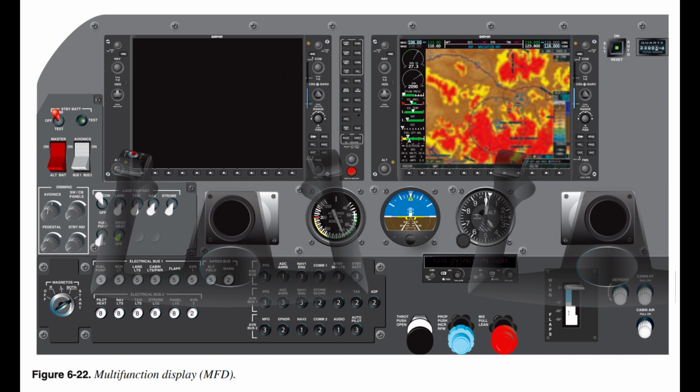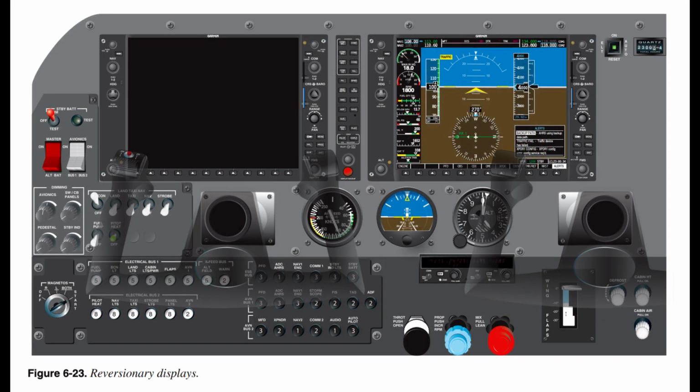The pilot can use the MFD to display navigation information, moving maps, aircraft systems information, engine monitoring, or should the need arise, a PFD, Figure 6.23. With just these two screens, aircraft designers have been able to declutter instrument panels while increasing safety. This has been accomplished through the utilization of solid-state instruments that have a failure rate far lower than those of conventional analog instrumentation.